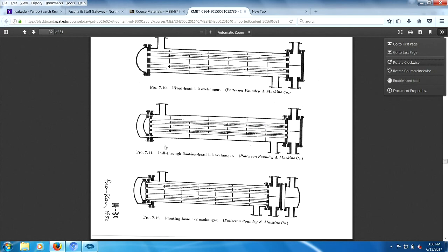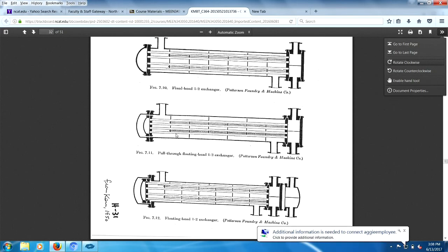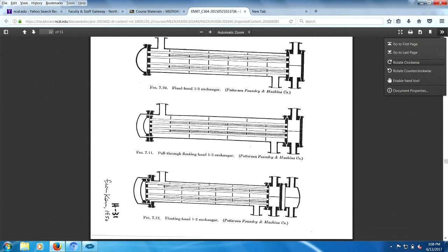You want to put the fouling material inside the tube. First requirement of design. That way, a design suggestion, I should say. And that way, tubes are real easy to clean. Shell is quite complicated to clean. The flow pattern in tubes is real easy. The flow pattern in shell side is quite complex, quite difficult to specify.